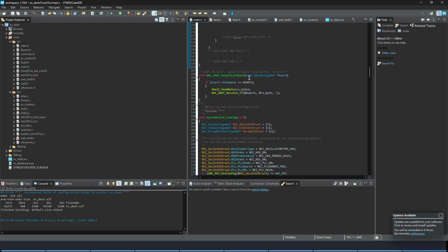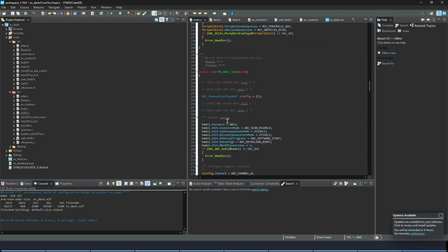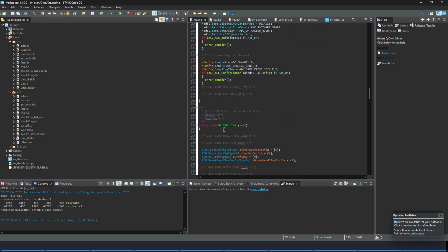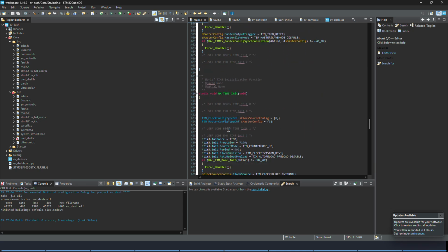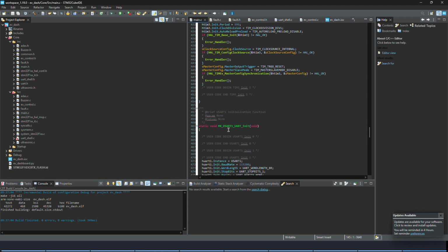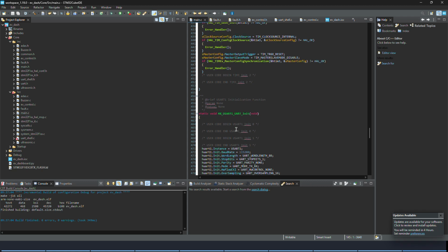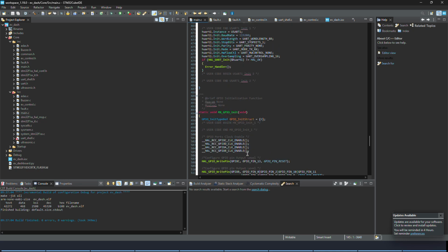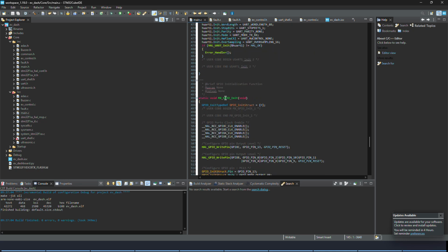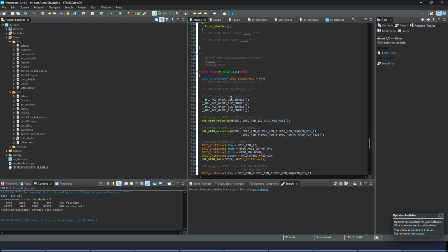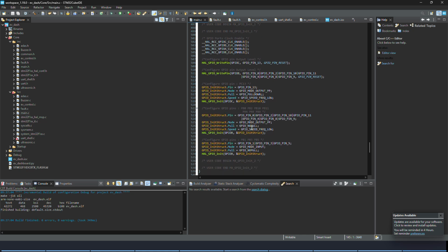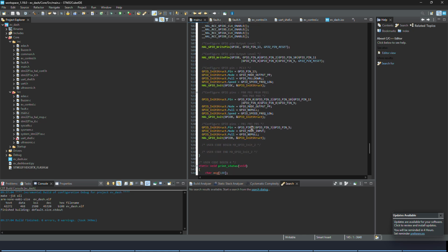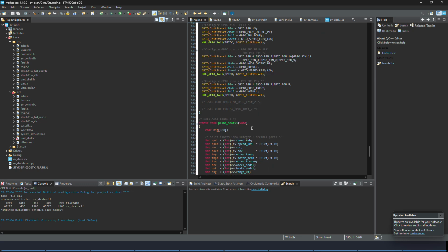We have three timers: timer 1, timer 2, timer 3, and UART 1 for UART communication. We have used a 115200 baud rate, and these are the general purpose input and output pins which I have configured for the ultrasonics and other components.